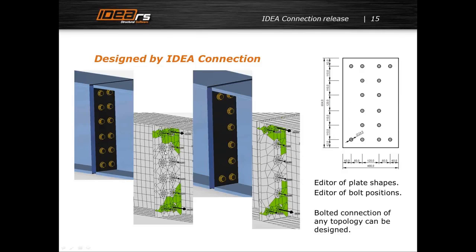Yes. About several things. The bolt hole diameter. It's always just fitting the hole indicated in the picture to the right. So when it's a bolt M24, there are always holes of 24 millimeters, at least in these overviews, in these drawings.